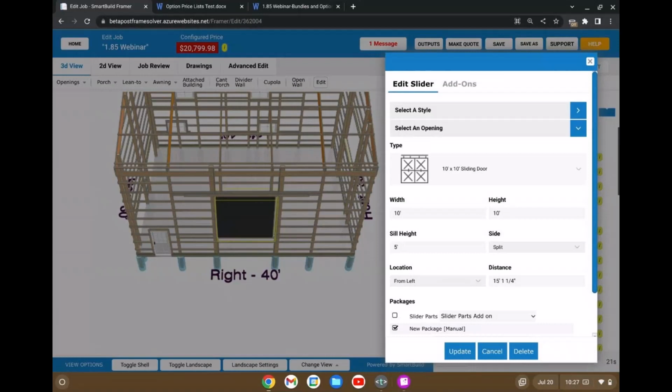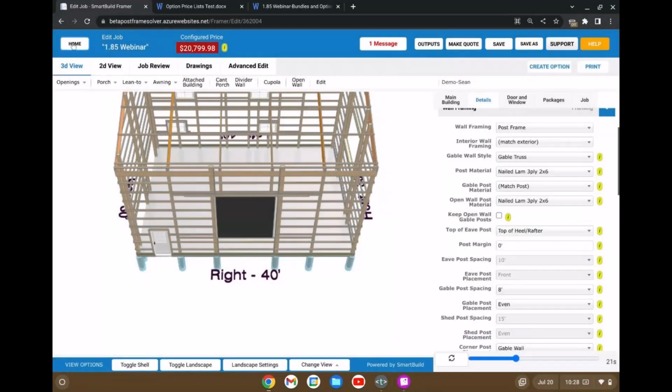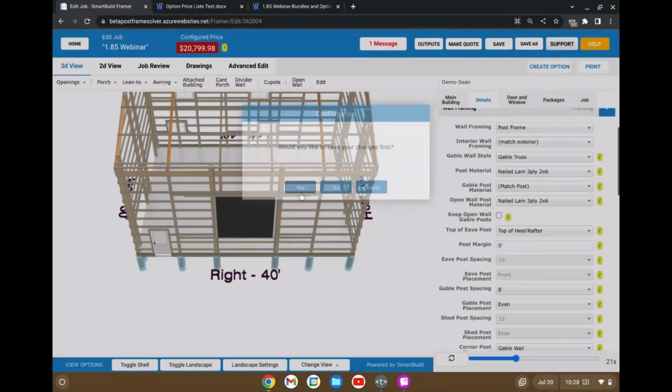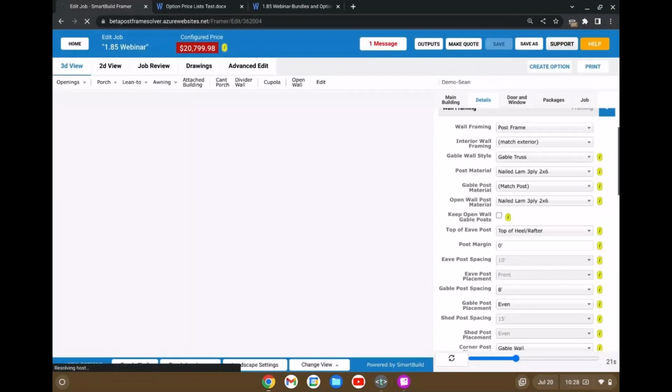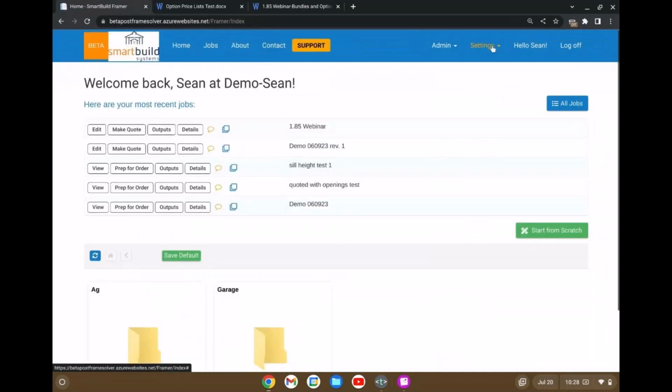Okay. We actually do that as well with a half-inch. We frame a half-inch under on the width and an inch less on the height. So all the overhead doors in our catalog are sized accordingly, and then it frames accordingly. Right. Okay. So you put in a 10 by 10 sliding door. You would put it in as 9 foot 11 and a half by 9 foot 11 and a half. We would just do 1 inch less all the way around.